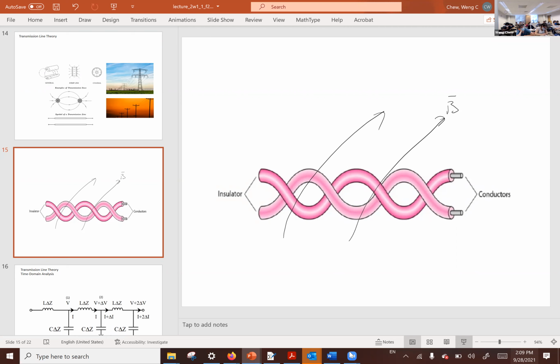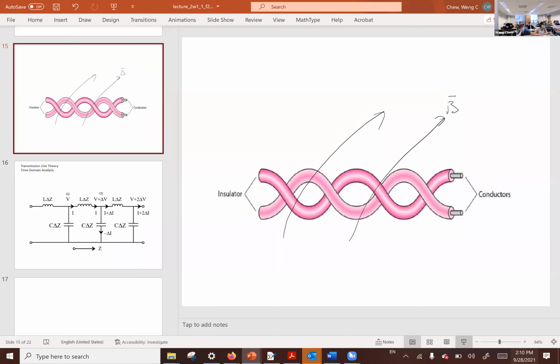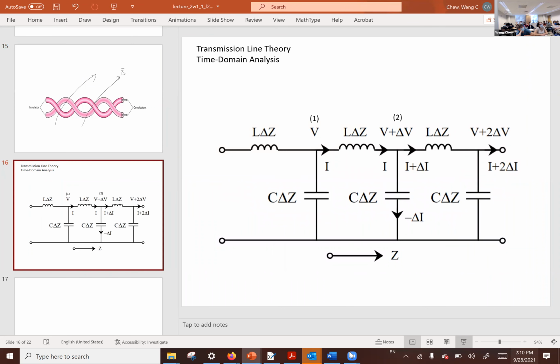Then the mystery is, why is it that we can transmit information? How does that happen? In order to understand that, we can start with the lumped element picture. You can take any two pieces of wire and break them up into segments. Each segment can be approximated by an inductor, and then a capacitor in parallel in this manner. Why an inductor and why a capacitor?